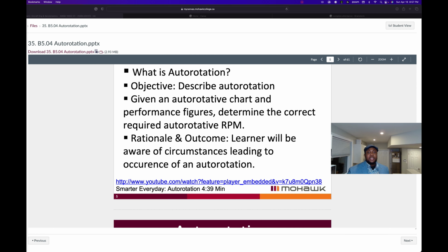During auto rotation, low RPM is a dangerous condition. If it's not corrected, it will leave very little kinetic energy in the rotor for deceleration and touchdown. The mass of the rotor system contributes to the rotor RPM throughout this sequence. So let's talk about different designs. Rotor system mass along with the speed contributes to the amount of inertia produced by the rotor system. So we have a high inertia rotor system versus a low inertia rotor system. What are these exactly?